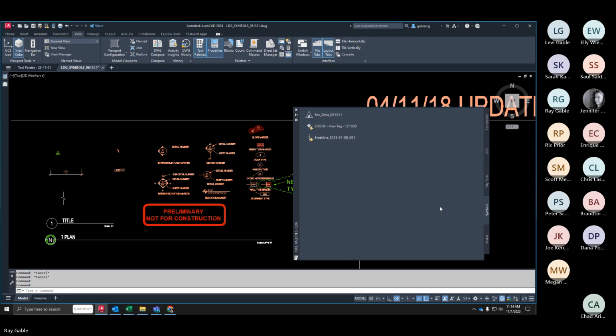I see so much copy and paste that some of the scale factors on there are just mind blowing. So it's always nice to actually start from the beginning. It makes everything much easier, especially when it's printing. And you know what, if it's the wrong scale, we can go in and put the scale factor in rather than to try and figure out what someone's done, copy paste, and then really understand what they were doing. And then all of a sudden it's in a drawing and you can't read it.